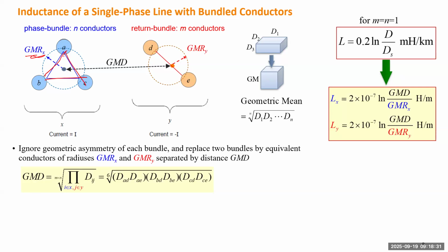Definitely those are 3 distances between the 3 conductors, but we also need to consider the distance between one conductor and itself. Which means we need to first define a reference, and for each reference we count all the distances, and by changing the reference we need to cover all possibilities. So let's select A as a reference.